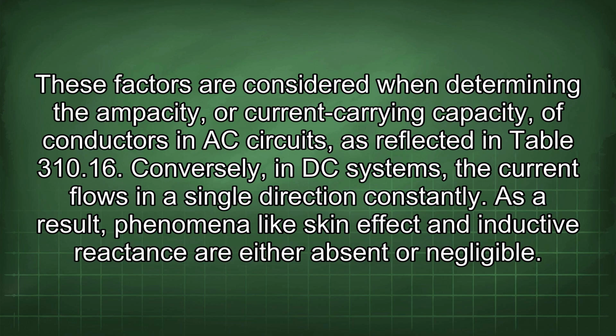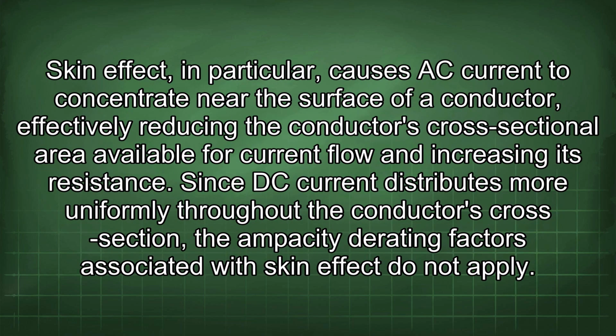As a result, phenomena like skin effect and inductive reactance are either absent or negligible. Skin effect, in particular, causes AC current to concentrate near the surface of a conductor, effectively reducing the conductor's cross-sectional area available for current flow and increasing its resistance. Since DC current distributes more uniformly throughout the conductor's cross-section, the ampacity derating factors associated with skin effect do not